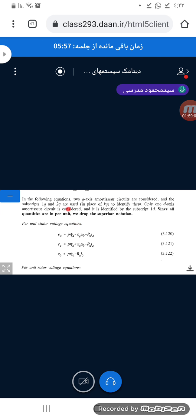In the following equations, two Q axis amortisseur circuits are considered and the subscripts 1Q and 2Q are used in place of KQ to identify them.